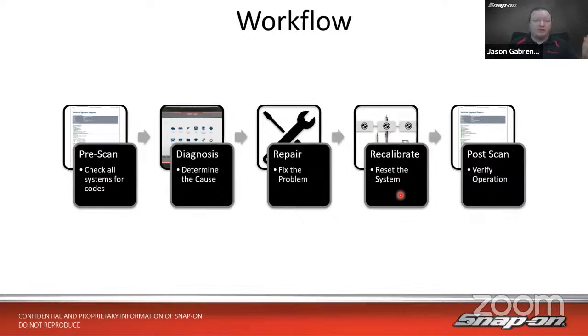I replace a fuel injector on multiple different vehicles. You need to type in a code. You need to recode the injector to the vehicle. Another one that always springs to mind is 06 and newer GM vehicles.